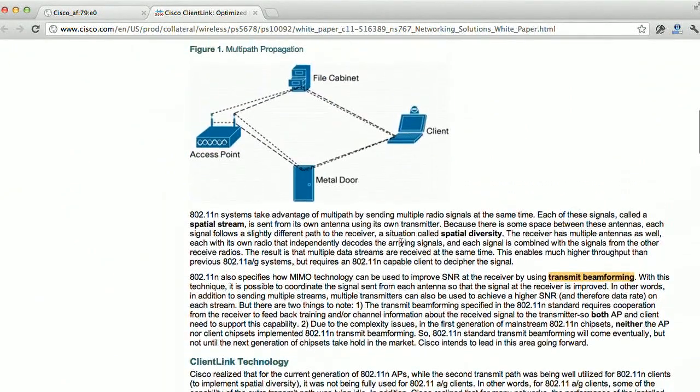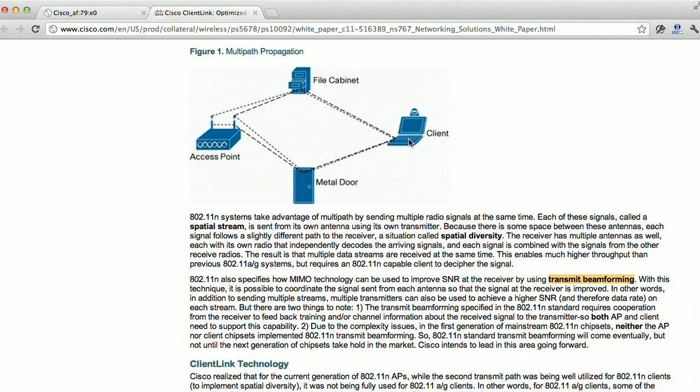We also talked about how, if the client had multiple antennas, they could use MRC, maximal ratio combining. They benefit from having multiple radios. Let's say we sent 3 or possibly 4 antenna signals out of an AP, they could hear 2 or 3 or 4 possible signals, hear each individually, and then combine them back together. That's MRC. And the number of antennas to the number of receivers is what we refer to by something. So let me just draw this real quick.